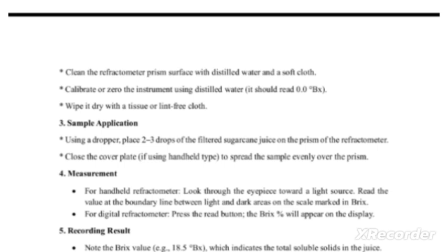Purity calculation. Purity is a crucial parameter in the sugar industry that indicates the proportion of sucrose in the total soluble solids in a sugar juice or syrup sample. It is expressed as a percentage, and higher purity means a high concentration of sucrose relative to other solids like reducing sugar, salt, and organic matter.